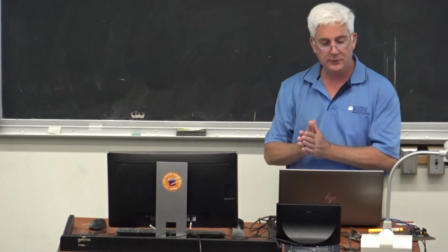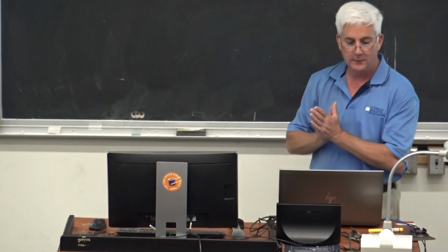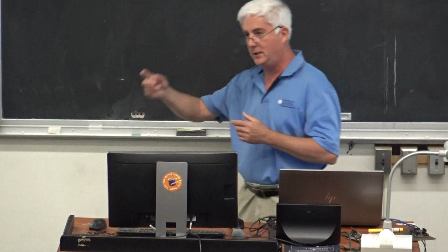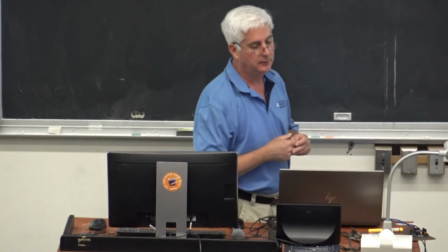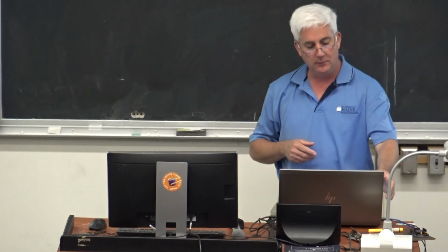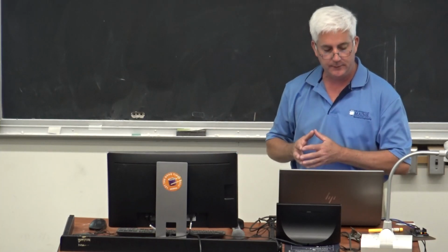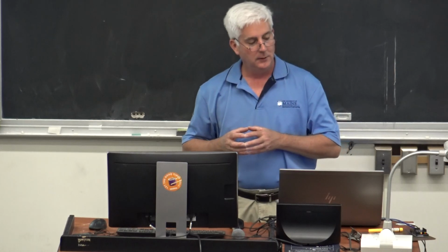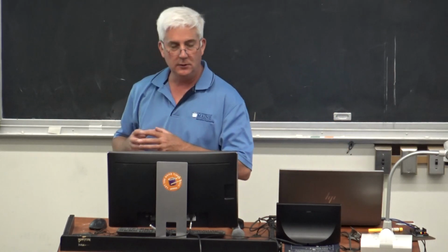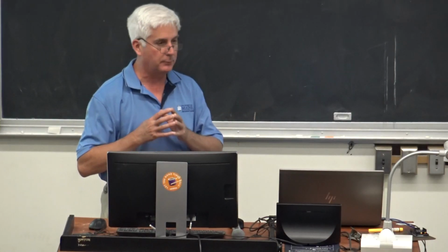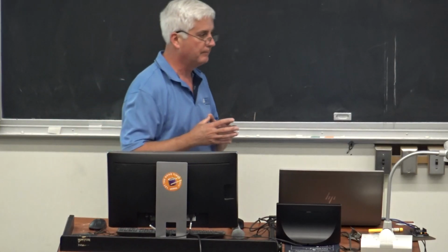Now we start actually doing the program. So void loop, this is the thing that's going to happen over and over and over again. So the first thing we do, we say time equals millis. Millis is a command, and it says return the number of milliseconds the program has been in operation.